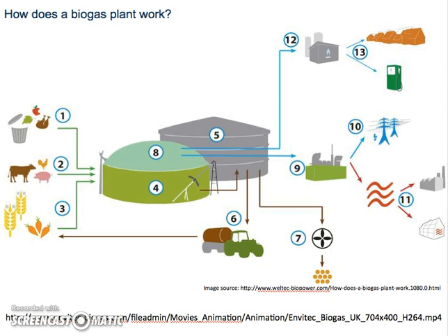The temperature inside the digester is controlled to keep the substrate at a constant temperature. The bacteria breaks down the substrate to release biogas. Methane is its main component. The gas is captured above the substrate in a domed roof area. The residue from this process is collected in a storage tank, number 5.